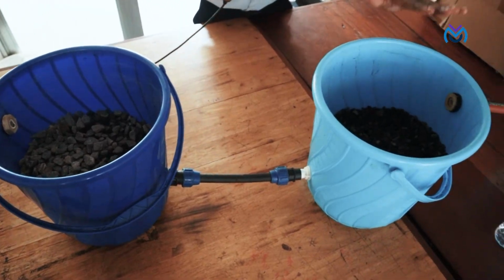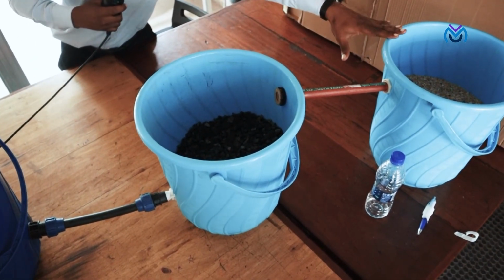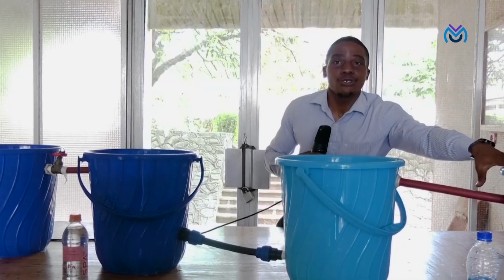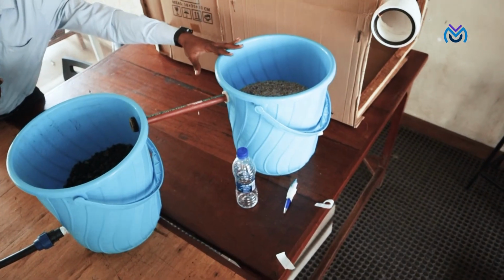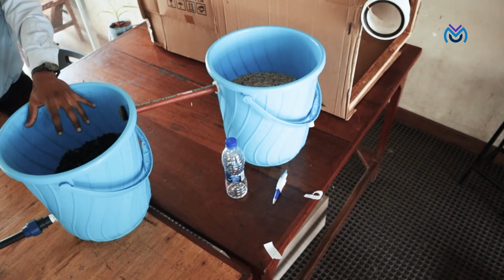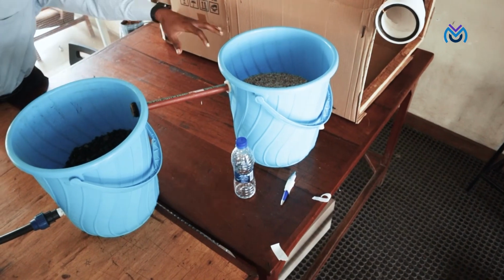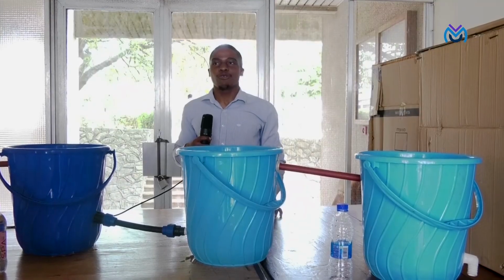Finally, as the water comes from this filtration tank, it will enter the last tank, which has sand filters. The sand filtration also further treats the water by removing sediments that were not able to be removed in this tank. From there, then the water can go into the tanks for storage.